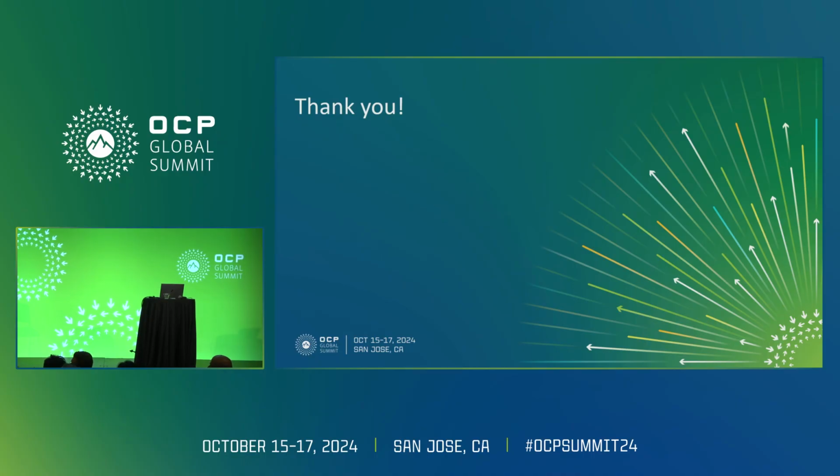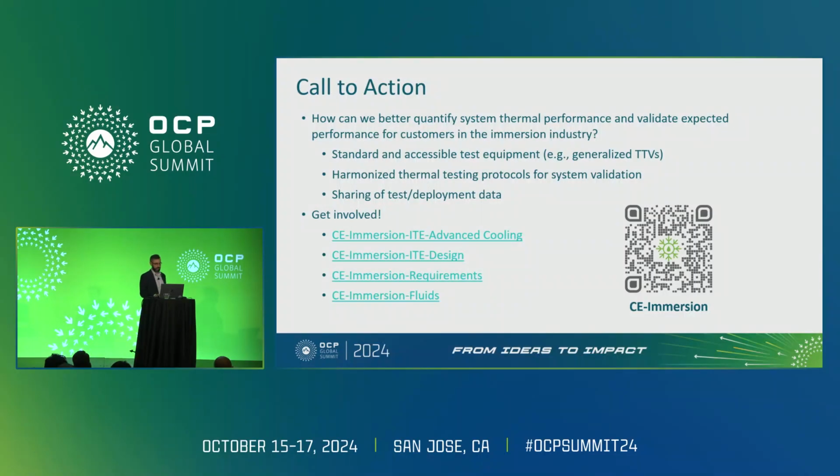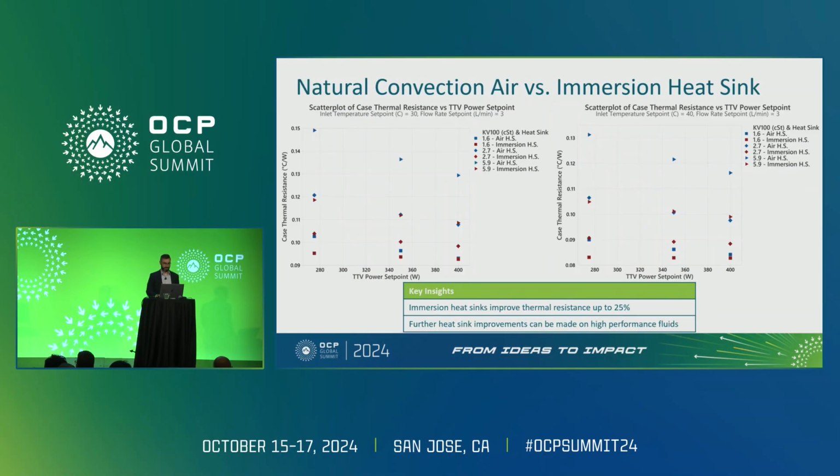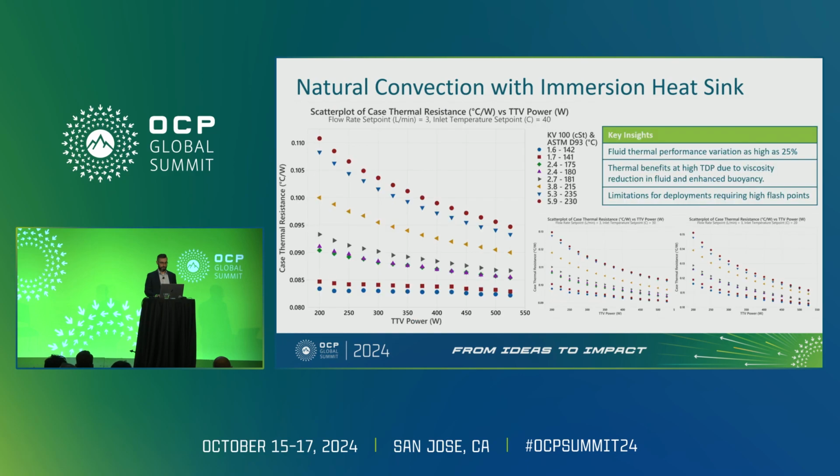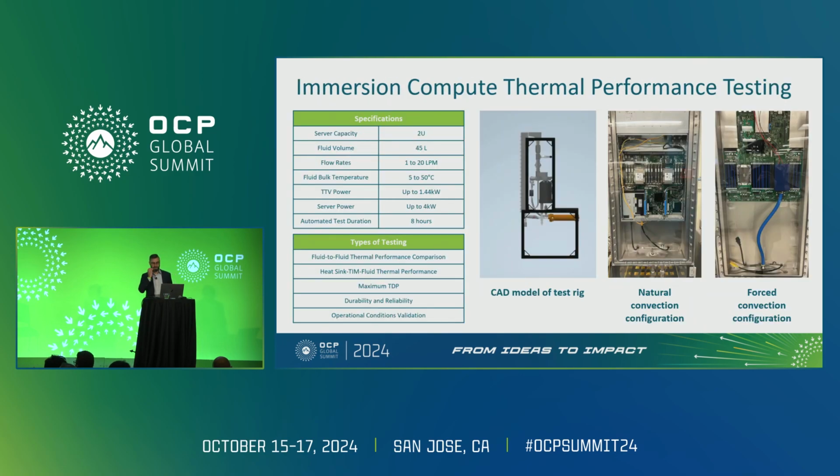I have a question about the test rig itself. I'm wondering if the surface geometry inside the thermal test rig can be modified to mimic the latest design in the server. I think the flow resistance in your system has a big impact, as it's closely related to the surface geometry of the chips or any kind of hardware inside it, and that will have a big impact on flow resistance and also on the Reynolds number that you use.